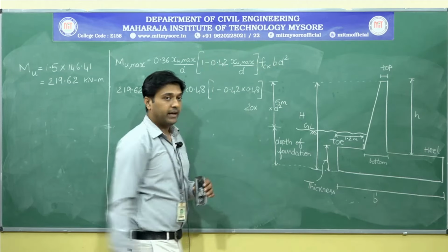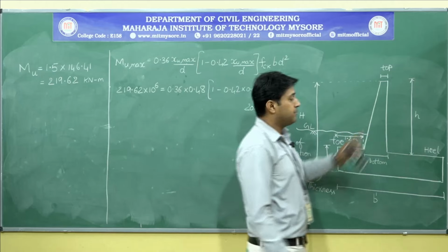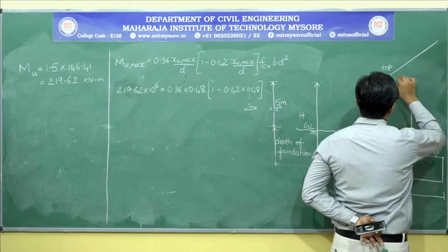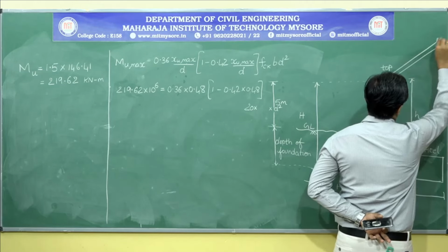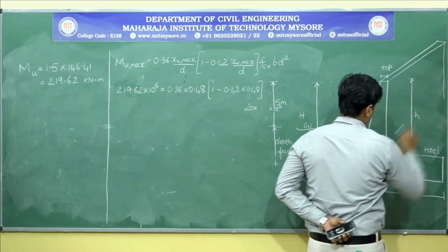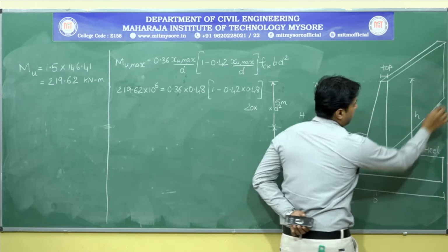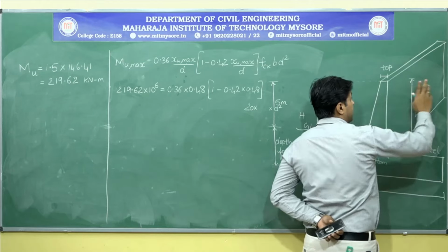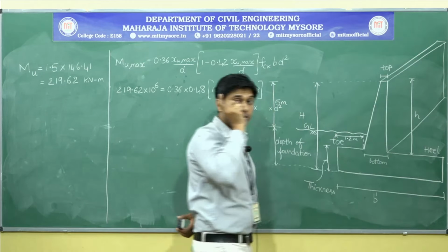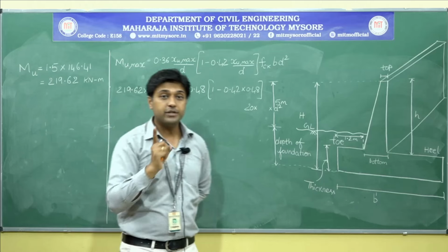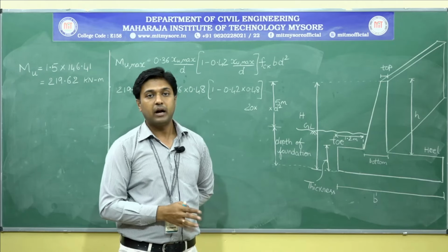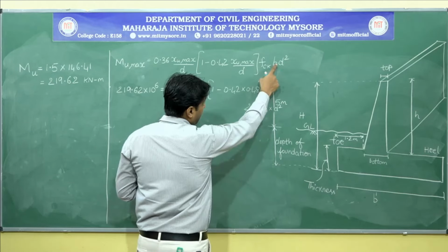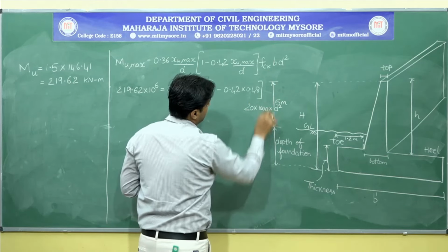What is the breadth that I need to take? I am concentrating on the stem. Observe here, if I try to write the 3D picture of this, try to understand this. It will continue like this. So this is the stem portion. It is almost like a slab. In a slab, we always go with the spacing of bars. So always remember, in a slab you need to consider breadth as 1000 mm per meter.